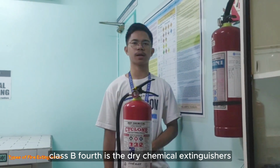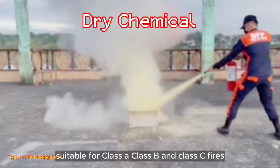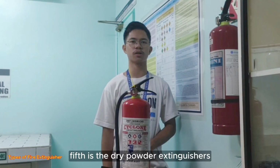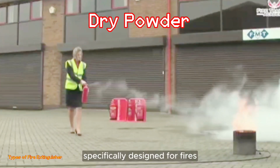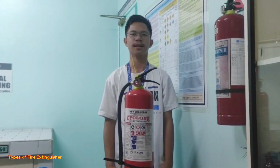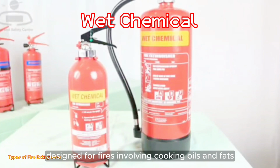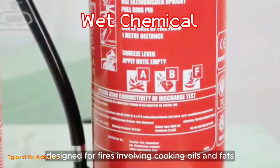Fourth is the dry chemical extinguishers, suitable for Class A, Class B, and Class C fires. Fifth is the dry powder extinguishers, specifically designed for fires involving combustible metals. Lastly, sixth, wet chemical extinguishers, designed for fires involving cooking oils and fats.